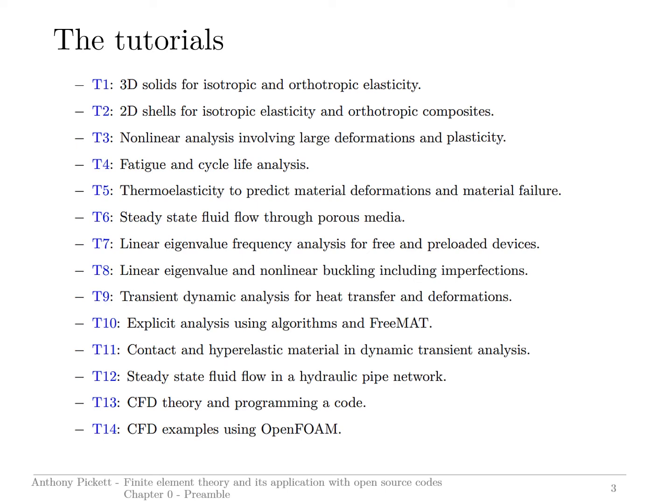It ties together the way you would do a linear elastic analysis to predict peak stresses, and how these peak stresses can be used together with fatigue curves of a material in order to estimate how many load cycles it would take before the part would break. I do include some theory there, so it's interesting for anyone who wants to get an overview of fatigue analysis with finite element codes.